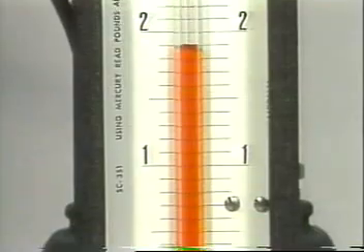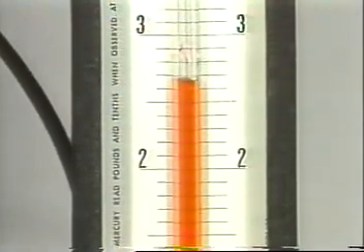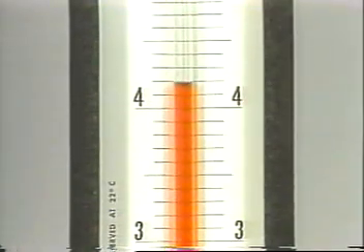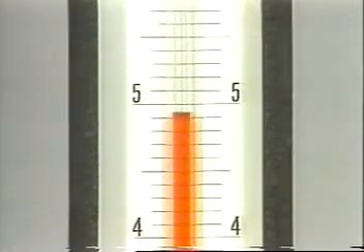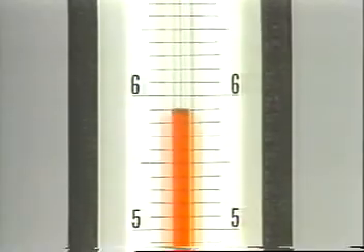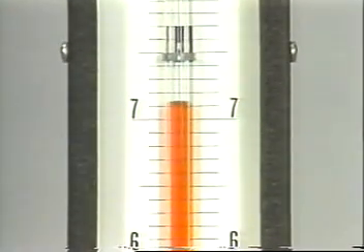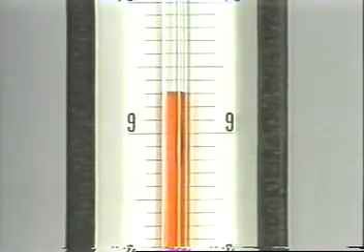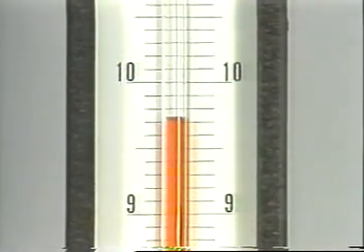As the pressure on the liquid changes, it causes the liquid level to change until the hydrostatic head of the liquid in the manometer equals the pressure being applied. The pressure value is read in inches of liquid. A change in pressure of 1 psi is equal to a change of 27.7 inches of water.